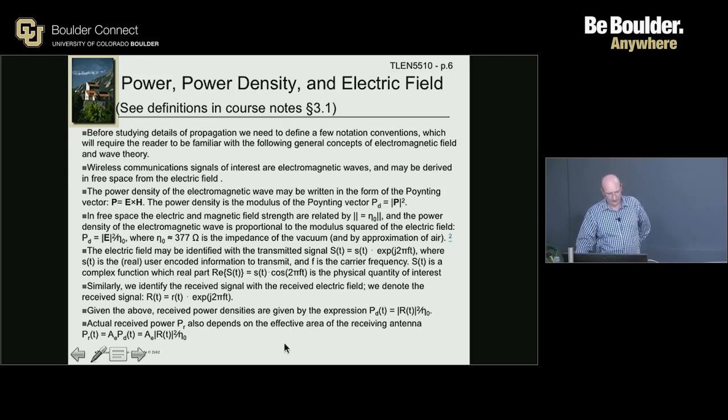And on the receiver end, we're going to receive r of t cosine 2πft, which is the complex exponential r e^(j2πft). And of course, between S and R, there's going to be a bunch of attenuation problems, etc. We could make things a little more complicated but more realistic by saying, really, we usually transmit two signals at the same time, right? A cosine and a sine. But for now, let's just say we just transmit a cosine. Everything else happens the same. We can expand on that later.